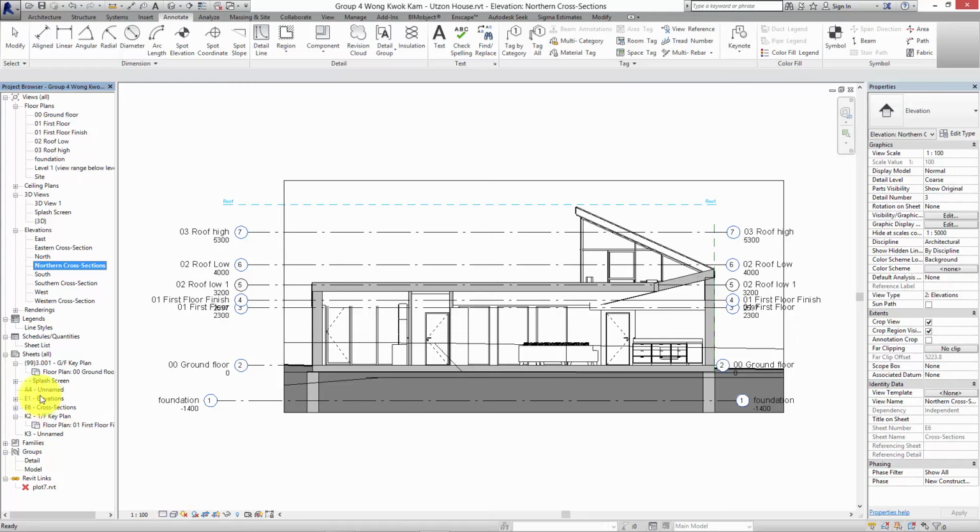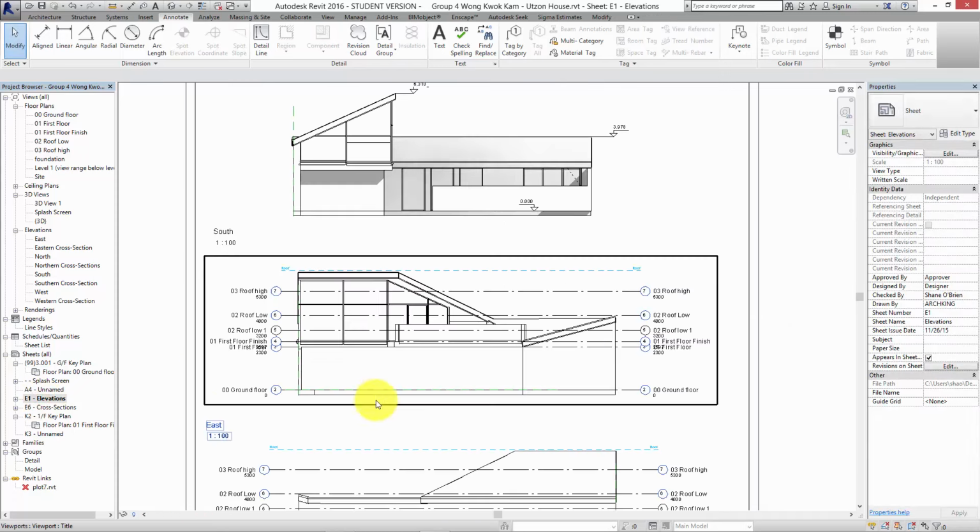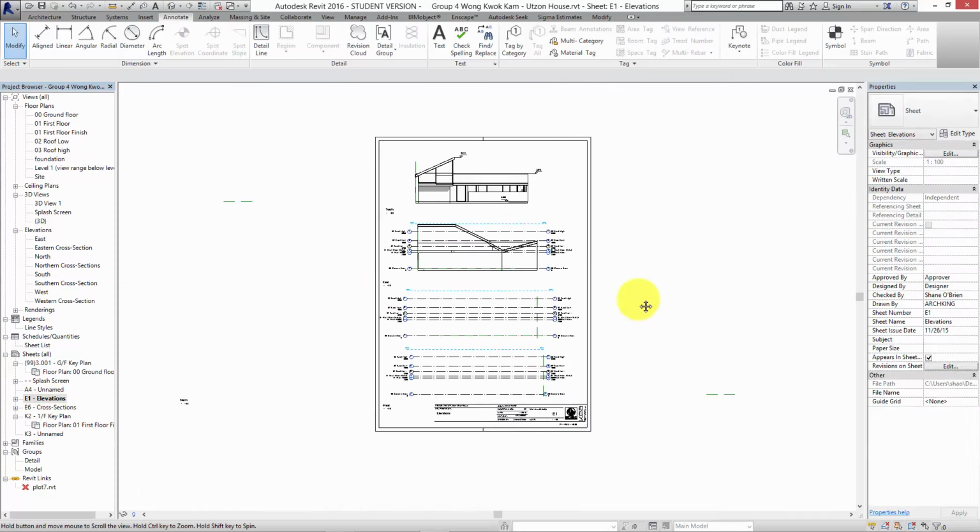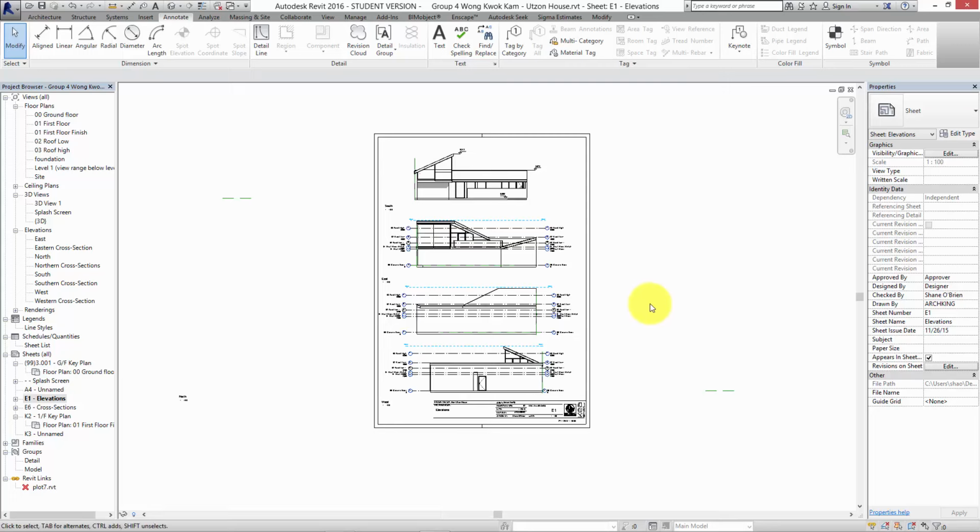And if I go back into the elevations here, it's usually the case nowadays that, well, in a concept drawing it's not so important, but for later stage drawings, you don't put more than one drawing on every individual sheet. You have a sheet per elevation. It's to do with filing and legal. So if you have a 1 to 50 elevation, it's going to take up pretty much the whole A3 sheet. If we did it as an A1 size concept board, I would do it like this. But when we get to the technical stages, it's usually one drawing per sheet, because it's easier to find in your filing system where each sheet is.